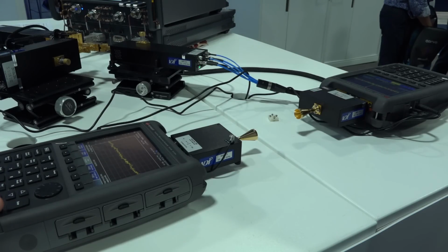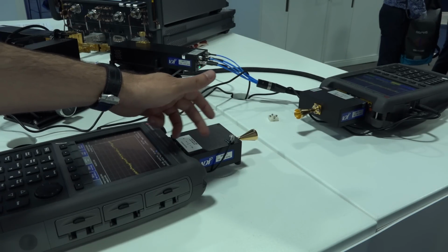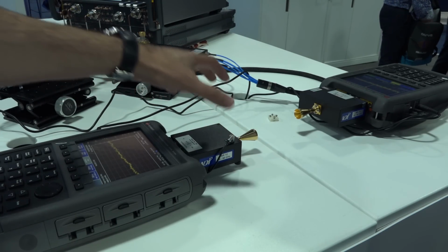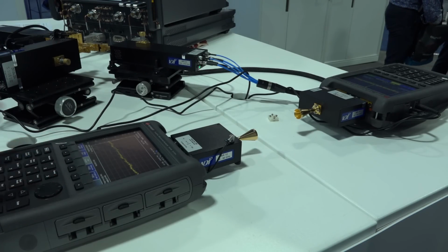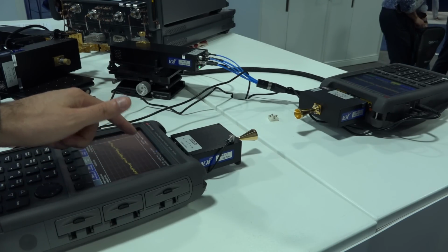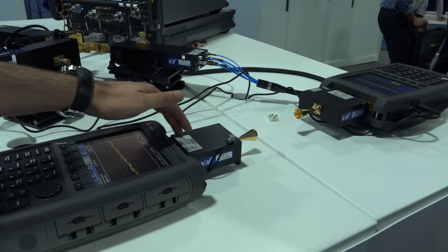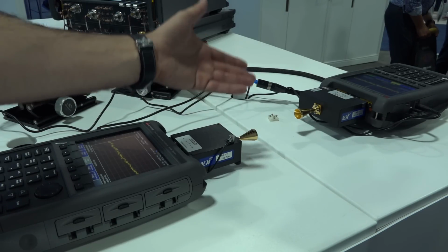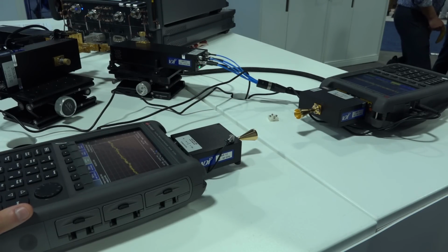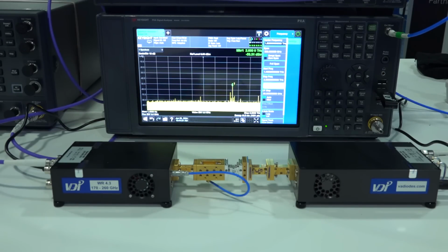And these extenders are also now available from VDI. This particular one is between 60 to 90 gigahertz, and you can connect it directly onto the FieldFox, and all the coefficients and everything will be set up. So essentially extending the frequency of the FieldFox quite easily. And this is a 26.5 gigahertz instrument, so obviously multiplication, a factor of 6, is used here to be able to do this. And using this technique with various horn antennas, you can now do OTA measurements directly in the field using multiple FieldFox.